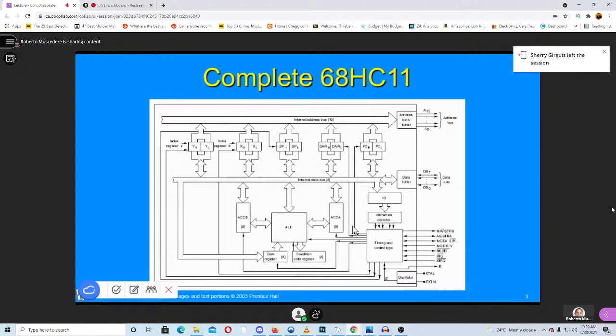Each one of these signals is determined by the microcode of each individual instruction. Each individual instruction, as we've seen, has a number of clock cycles required for it to fulfill its work. So this part of the circuit is probably the largest, although you wouldn't think it is by just looking at the block diagrams here.